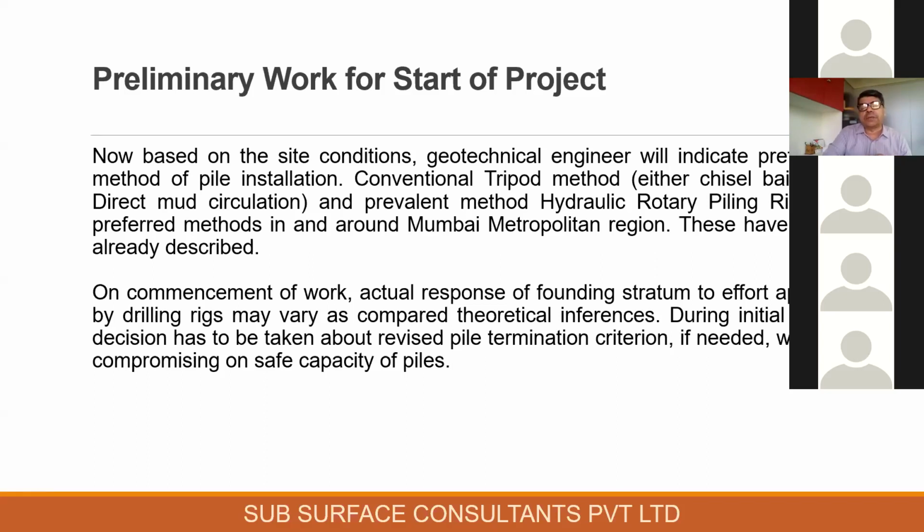Typically, ideally, I would say that when the geotechnical investigation data is correct, accurate and reliable, you will find that fair judgment made by a geotechnical consultant will yield the same results. Supposing a geotechnical engineer has defined that we go for 5 times pile diameter, you will generally find that if the data is reliable and of good quality, then similar pile lengths will be achieved. They might change by a small amount here and there, but they will tally.